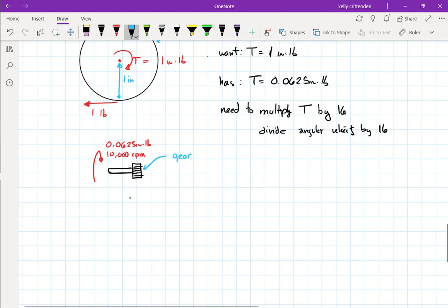And we're using gears because we're going to make the assumption that they won't slip. For a gear, there are actual gear teeth that mesh with one another. You could have pulleys, one diameter pulley and another size diameter pulley. The problem with that is the belt that connects those two pulleys really could slip, and we don't want to deal with that right now. We want to assume that there's no skipping teeth between our gears.